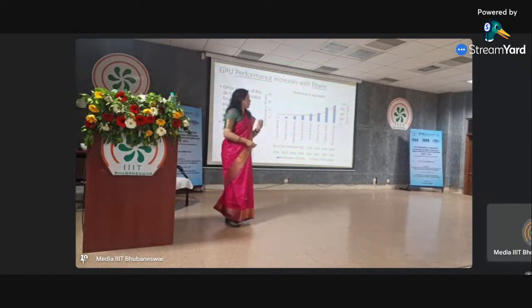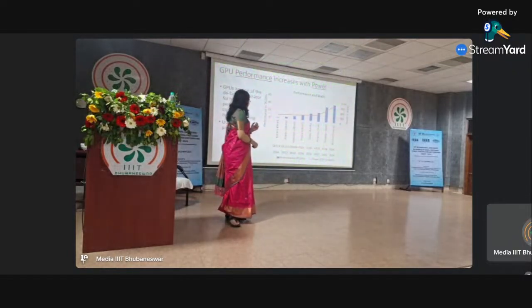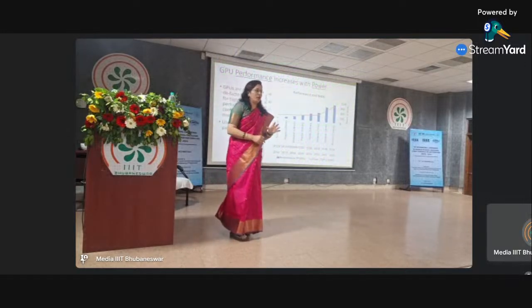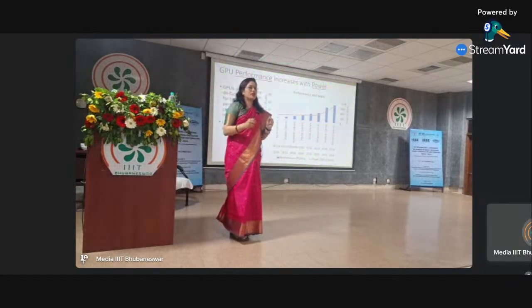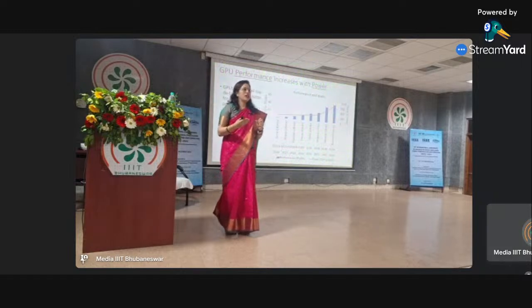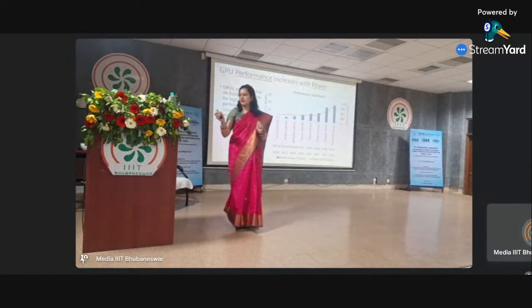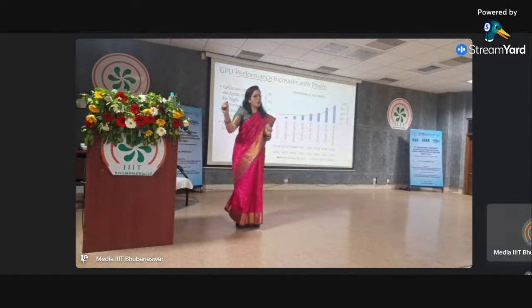Earlier, like 20 years back, we were only concerned about the dynamic power. Dynamic power means how many times I'm accessing a component; dynamic power is proportional to that. But static power is different: as long as my system is plugged into the power supply, even though it's not used, there is still a leakage current flowing all around, and it's consuming the leakage power, or the static power.